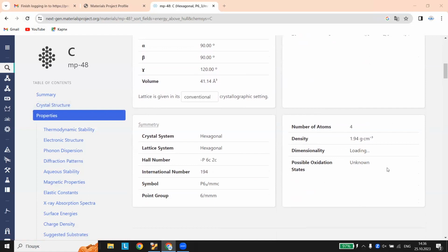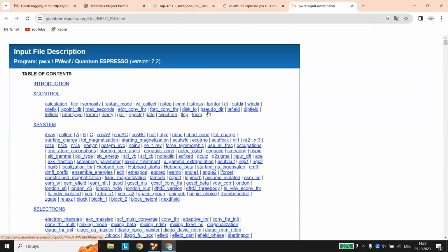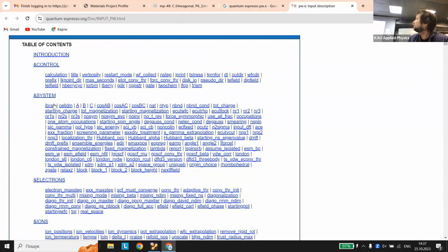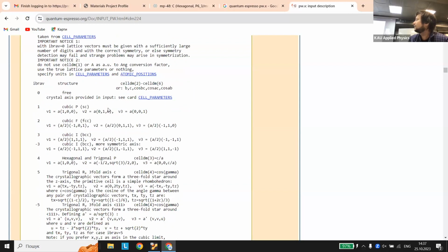You can open the pw.x Quantum ESPRESSO manual and check our ibrav. How can we fill it? Here you should find ibrav first, and you should choose your ibrav. Like in Mortal Kombat, choose your fighter, choose your ibrav. Hexagonal is 4. And you see, what celldm do we need for hexagonal?